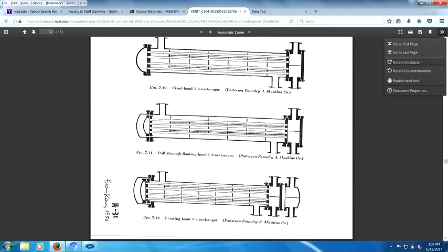They're put in there to direct the flow. There's two types of flow here. I mean, two flows. There's pipe flow, basically, or tube side and shell side. Shell side flow, perhaps the stuff comes in here, comes down. You want to go across the tube bundle. This will be a bundle of tubes.